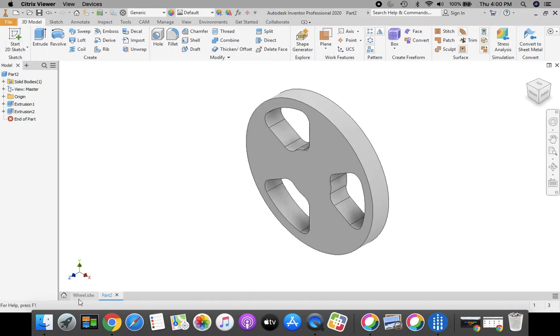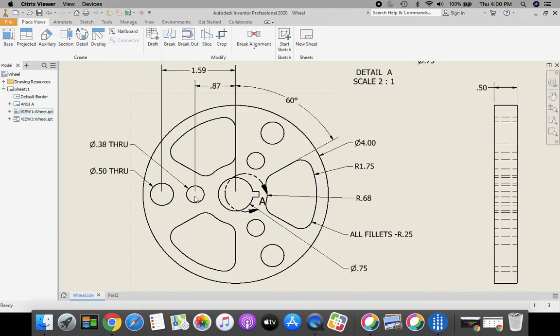Next, we're going to do these holes. There's a 0.38 and a 0.5 diameter hole. Now notice we're going to be working on our 9 o'clock side of the circle. The 3 o'clock side, we had this shape slot over here. Now on the 9 o'clock side, we're going to put these 2 circles and circular pattern them around. 0.38, 0.5.